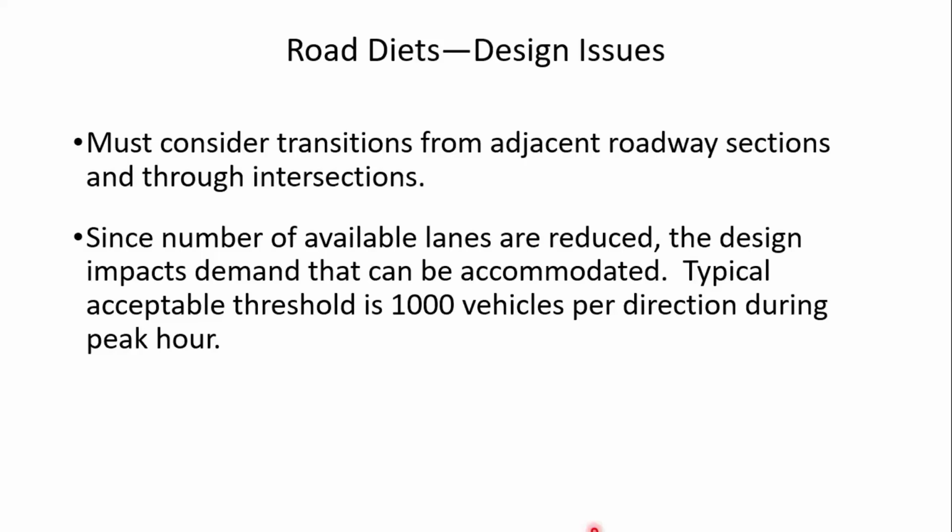That sounds well and good, but the issue is that this particular roadway carries right now about 35,000 vehicles per day. And that, to me, would not work if we had 1 lane per direction. So you do have to look at your volumes, and road diets may not work for higher volume roadways or arterials.